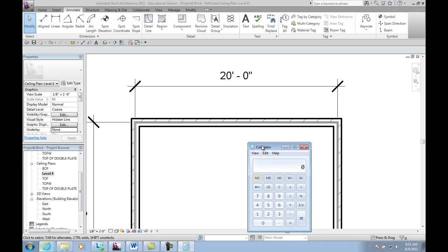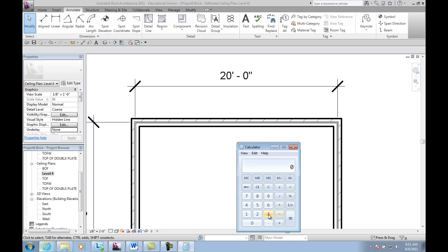Let's figure up our inches in this thing first. 3 5/8, 3.625, is 5/8. We've got to times that by 2 because there's 2 bricks, plus 2 airspaces, which are 1 inch apiece, so 2 inches. So 9.25. So this thing's going to be 20 foot 9.25 inches.